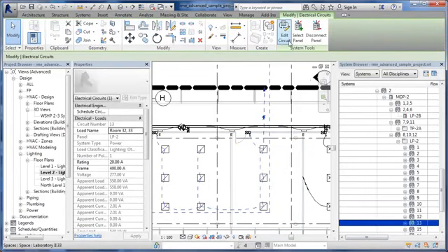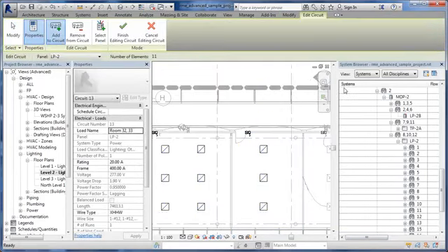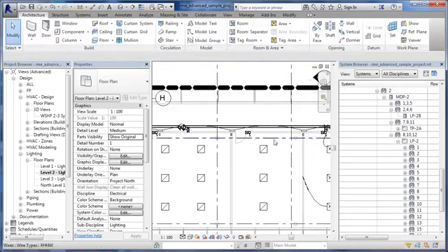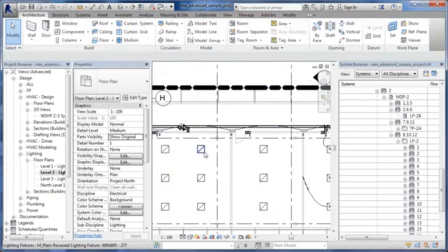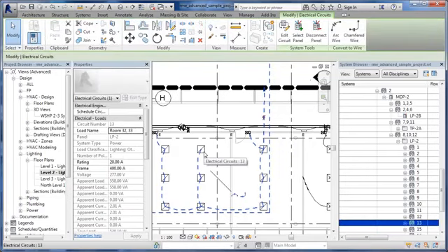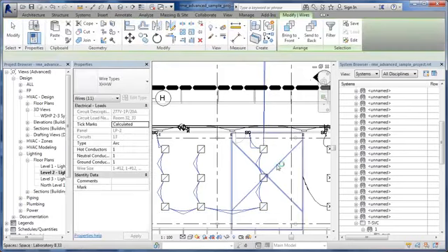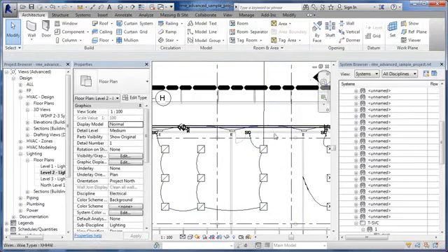Pick on it here, and I can say edit circuit, and inside of there, I want to add wiring. I keep forgetting the stage. Cancel out of there. Let's try it again. Circuit 13. So that's too high a level. Let's hit escape because there's different levels. Tab once, pick on here. That's where I'm going to get the wiring option. Add the wires, click out.